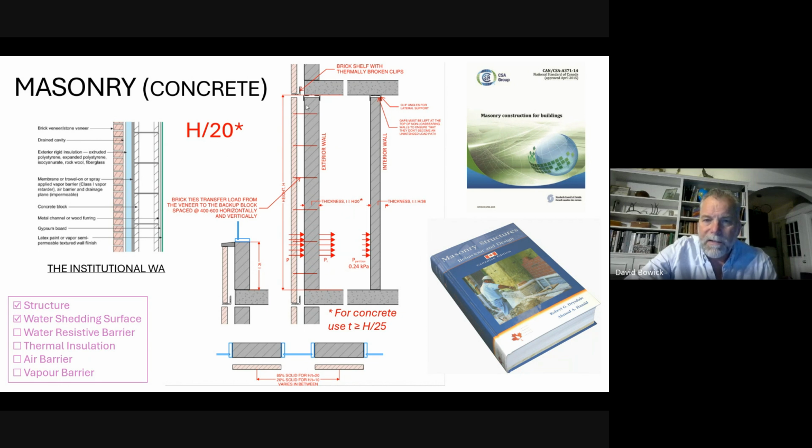Look at the detail at the top of this wall. The masonry doesn't go right tight to the underside of the slab. You've got two little clip angles at the top, and an airspace. What this is doing is it allows the upper slab to move relative to the lower slab, without that exterior wall becoming an unintended load path.